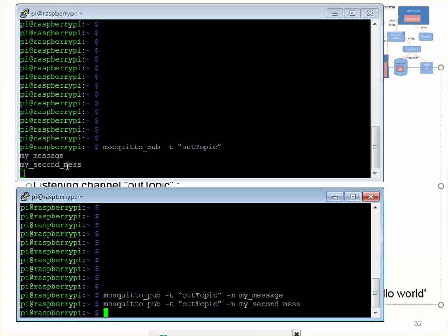And as I said, it doesn't matter if you send this from this terminal window or if your Arduino, which is connected to the same network, is sending messages to your server, the messages appear here the same way. And this is quite a nice way to track that your system, the Arduino sending system, is working before starting to try that Python program. It's worth trying this Mosquitto side, that it's running and working.